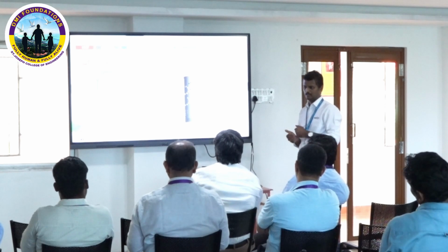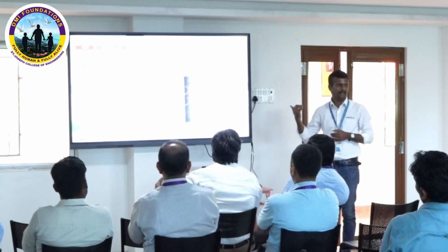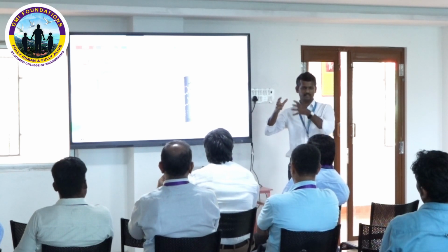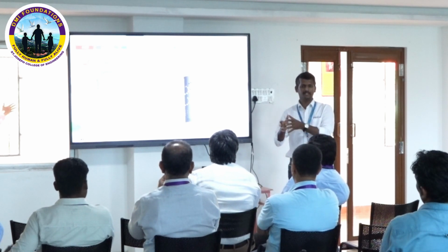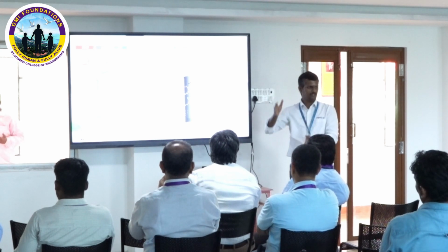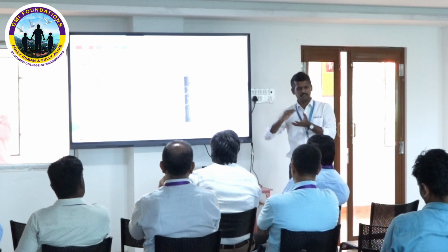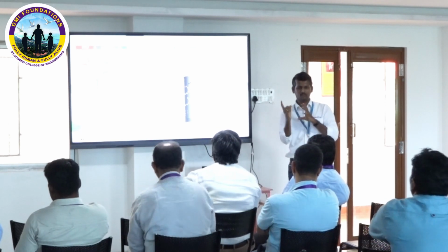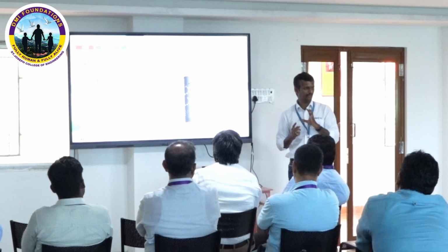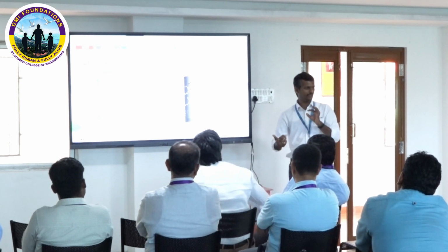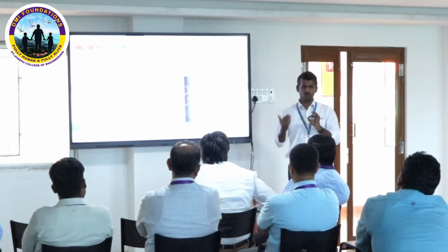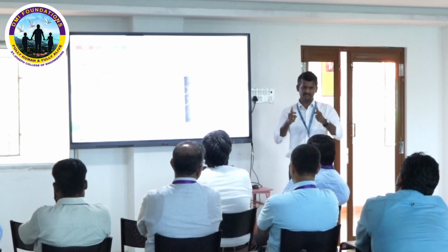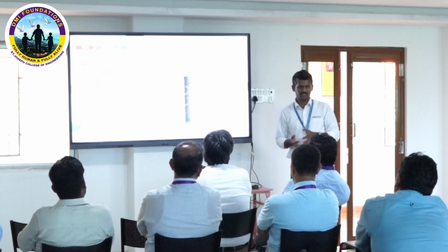Even recently, the PSLV stage 4 combustion chamber, right? The complete engine, we are 3D printing, and then the nozzle system also, so that it has conformal cooling channels inside of it. The cryogenic fuel which is being used will act as a coolant for the engine, and the injector is also created as one single system, right? Now the assembly times are very low.